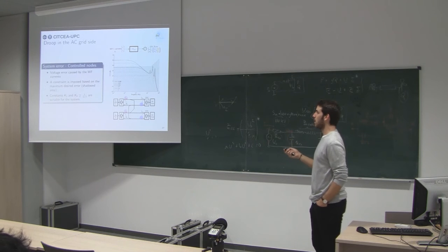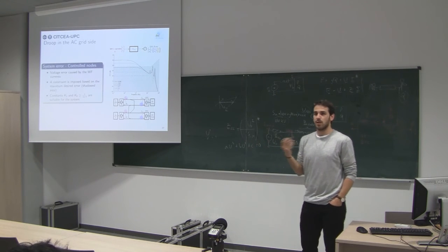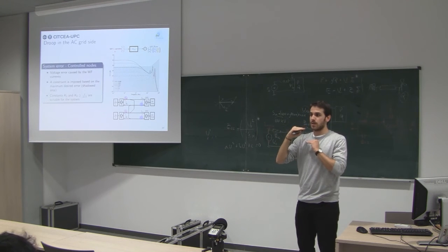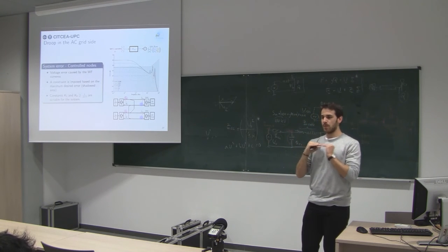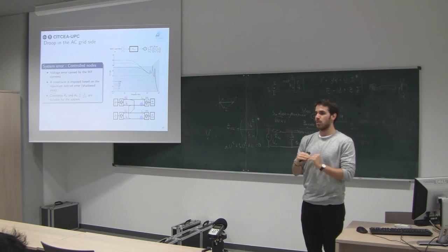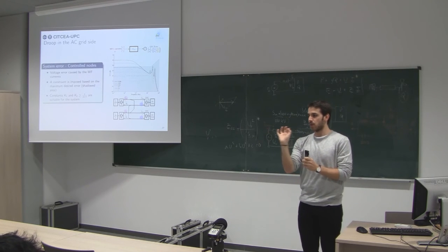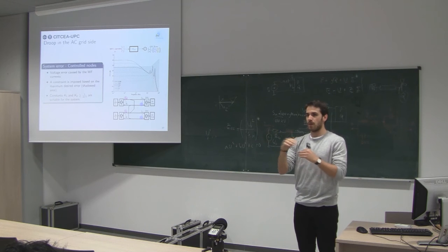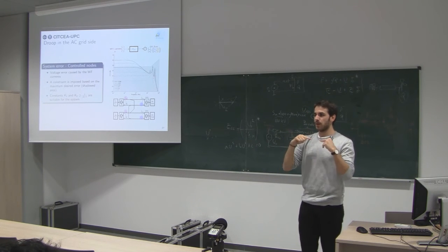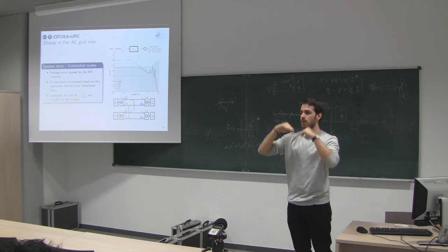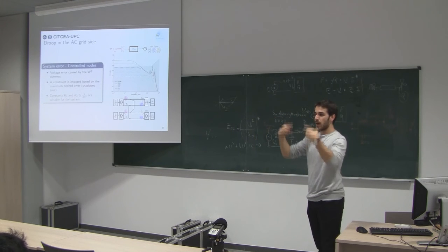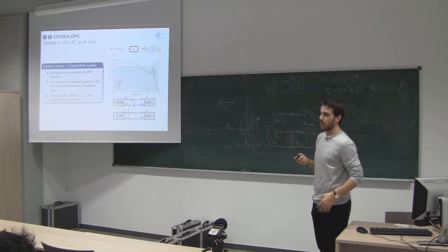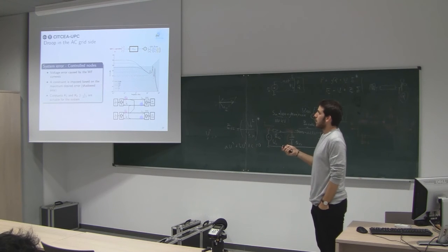So what we knew here was our worst case on the wind farm currents. If we have a step input at both, which is impossible, of course, but imagine a perfect wind farm that can increase the power in a step, from 0 to 400 megawatts at a certain instant. Imagine that you can establish a 400 megawatt step at both sides at the same time. That's the worst possible case scenario, and that's what we chose.